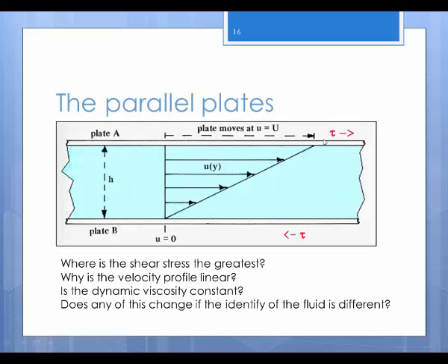This diagram illustrates how you could actually use Newton's law of viscosity to solve a problem involving shear force. So what if you wanted to know the force it would take to pull a plate on top of water, with a relatively thin distance between this stationary plate and this upper plate, and you knew that the area of this plate was 1 meter squared? Well, if you look here, this is the velocity gradient. How is du changing with change in y position?